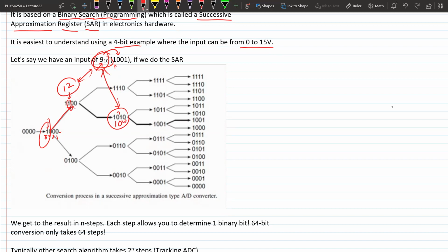So whenever my number is smaller than the input, I add to the approximation. Whenever my approximation is bigger than the input, I shift instead. So this is something you can do systematically, because in a circuit, you have to do everything by these systematic rules.